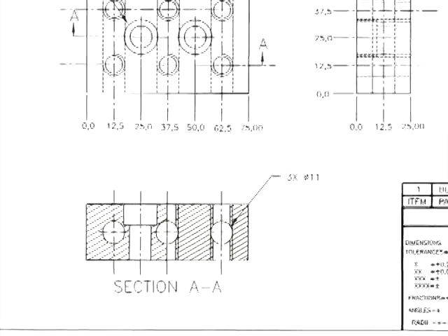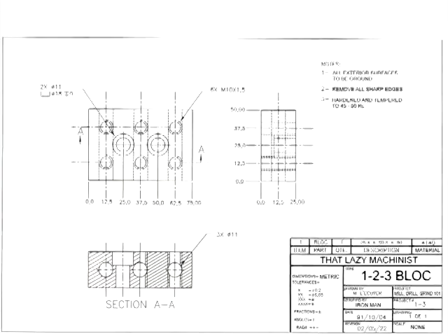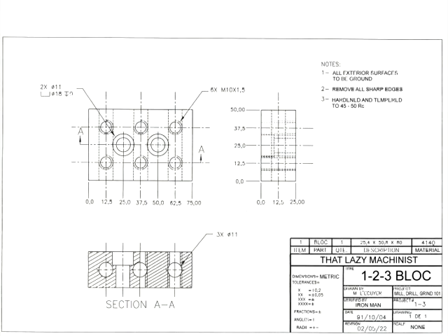Now, this drawing really only required two views. It could have been a front and bottom or a front and right or left side views. But I added to the front and right views here this section bottom view just to make things quite clear. So sometimes we'll even add a view to a drawing when we're worried that the views that are there are a little difficult to visualize.